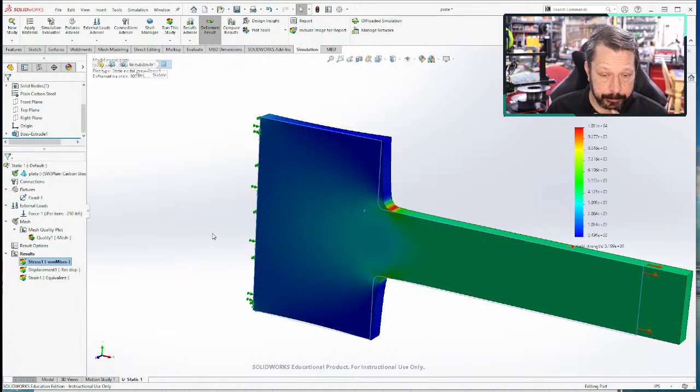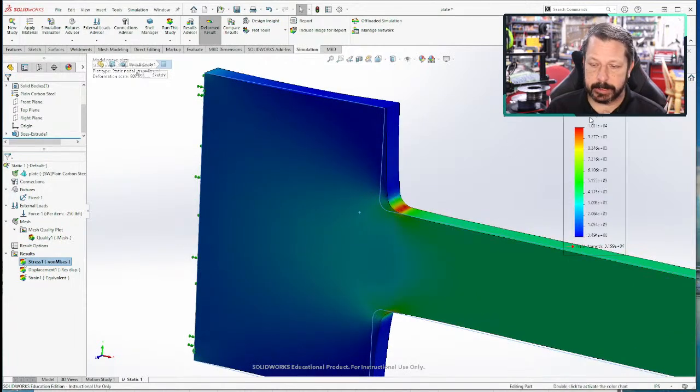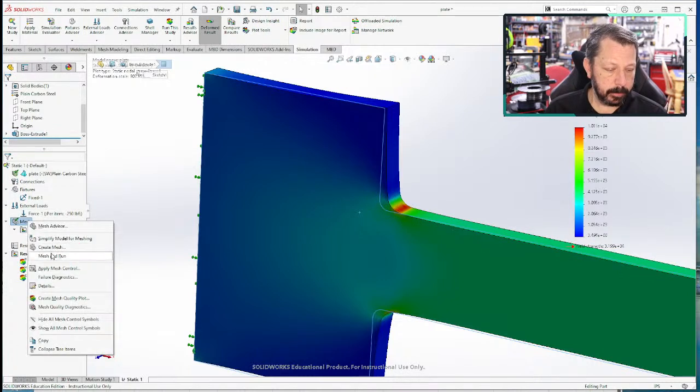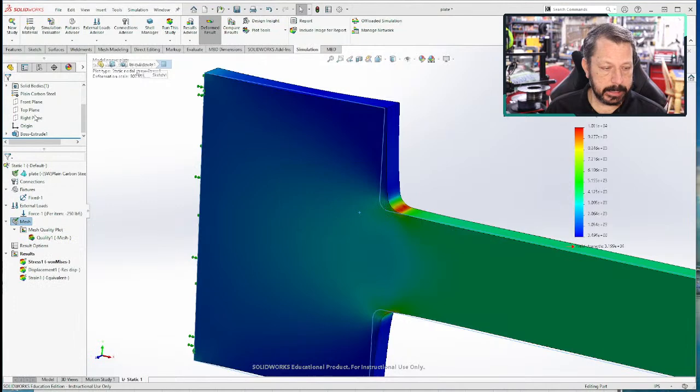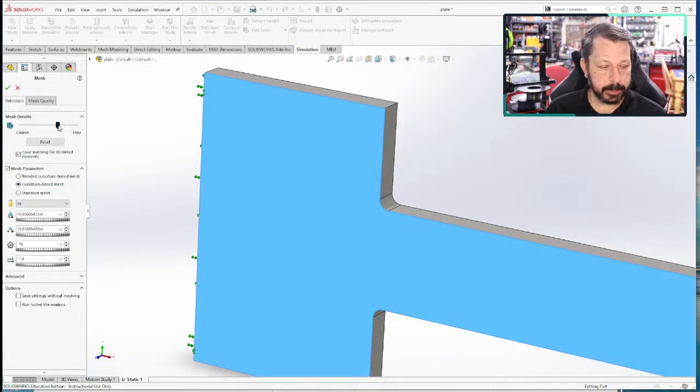One thing you can do is take a feature somewhere, not necessarily just grabbing the highest stress on your chart here, and run several different meshes. So you could have a coarse mesh, a medium, a little higher, and a fine mesh. And then wherever that feature is, interrogate your simulation results and find the stress of that feature as you increase the number of elements.